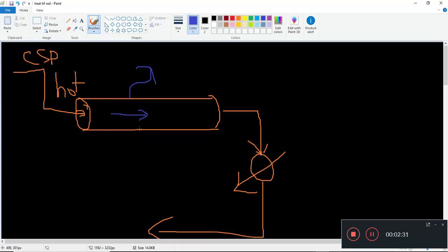As the salt goes through this pipe, there will be some convection that carries the heat away from the fluid to the surface, and then because the salt is so hot, radiation actually plays a role in getting the heat away from the salt to the cylinder surface, which is the pipe surface, and that contributes to how much heat is being lost through the pipe walls. So this is some of the relevant application to our radiation transfer equation.